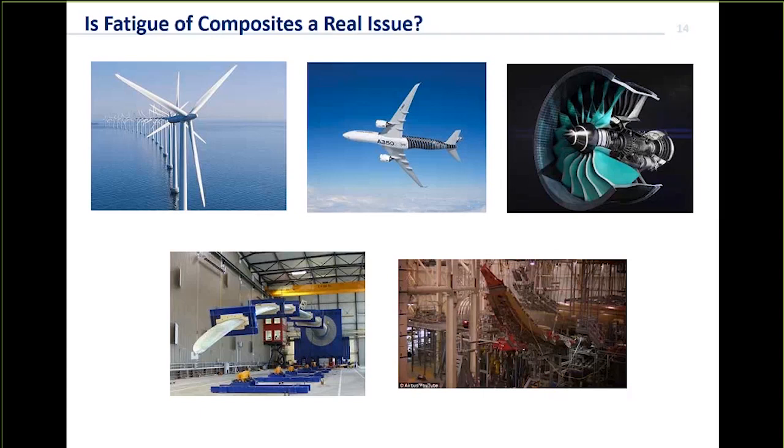There might be some cases where the dimensioning of a design is controlled by the static strength and stiffness alone, so that to the extent that fatigue is not an issue, but otherwise it is a concern. Composite materials can and do fail by fatigue, due to repeated or varying loads that are less than the static strength of the structure. So manufacturers need to find ways of avoiding premature fatigue failure through analysis or testing, or both, and ideally also optimize their designs through analysis.